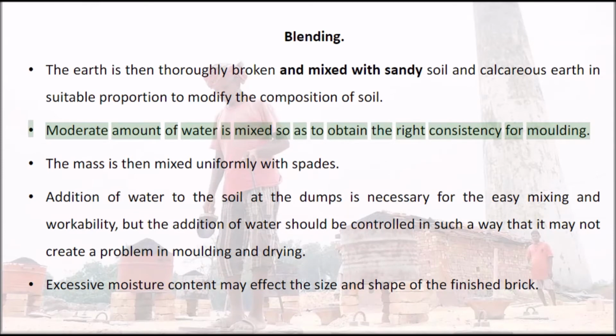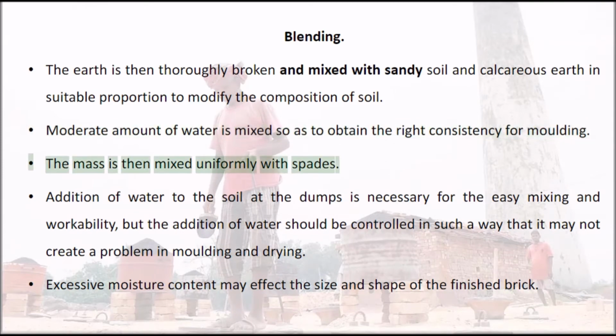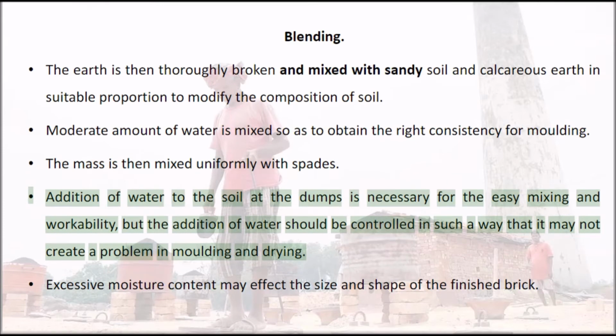Addition of water to the soil at the dumps is necessary for the easy mixing and workability, but the addition of water should be controlled in such a way that it may not create a problem in molding and drying. Excessive moisture content may affect the size and shape of the finished brick. Tempering.